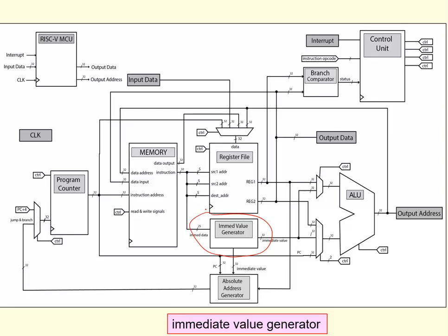Now, some of those field codes represent signed numbers, so I need to sign extend those numbers. Some of those field codes represent unsigned numbers, so I need to zero extend them. Keep in mind that there's also address data associated with branches and jumps, which, if you remember correctly, is stored as relative addresses, and it's stored as signed numbers. So essentially, that number is definitely sign extended.